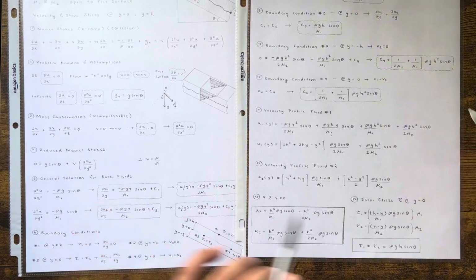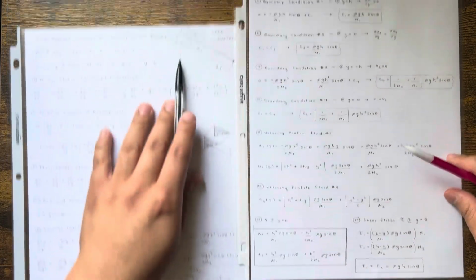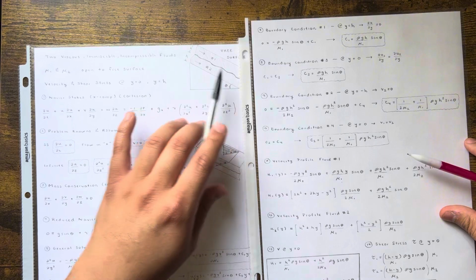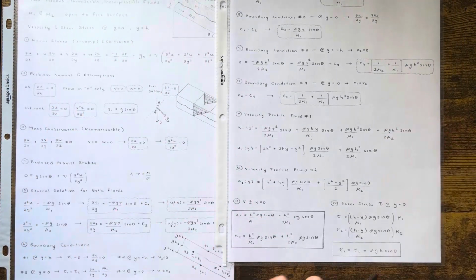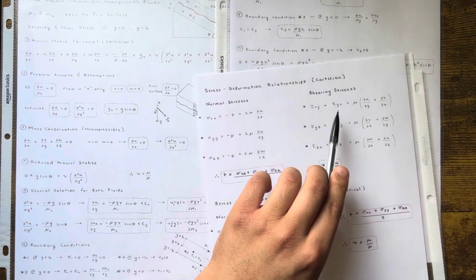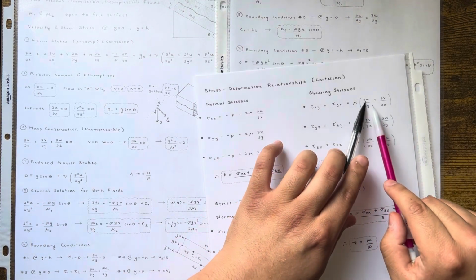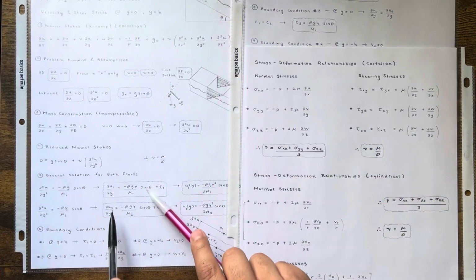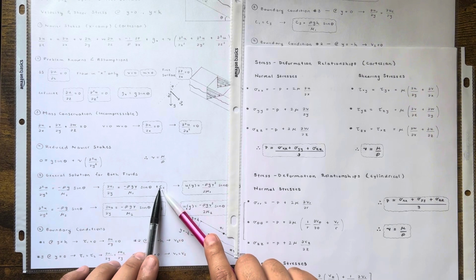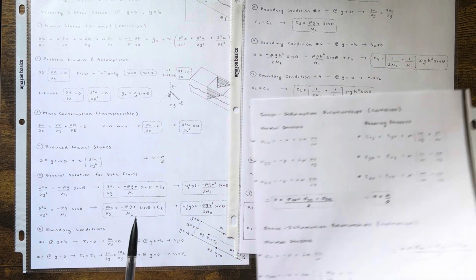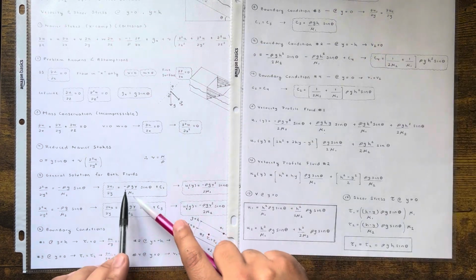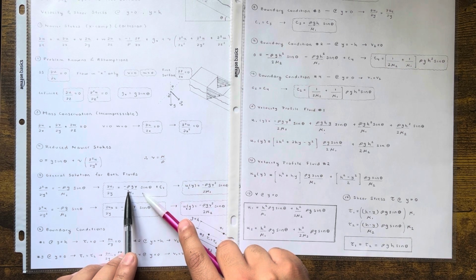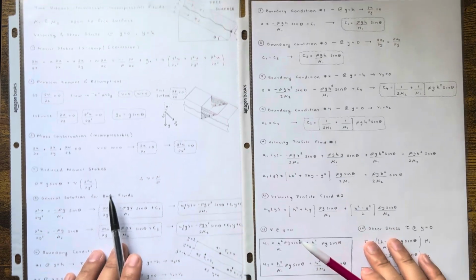Shear stress, and let's go ahead and get it at the interface. What is that shear stress value when the two fluids meet? Well, remember shear stress, we determined it to be tau is equal to mu times delta u over delta y. Well, what's delta u over delta y is these two, right? So in this case, I already have C1. So do the math. I'll just do it with you guys, my bad.